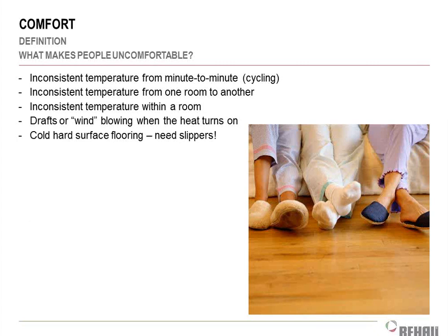Touching cold surfaces. If it's summertime, you like walking on the cold tile floor of your kitchen or whatever. But if it's wintertime, cold surfaces feel cold. Conductive heat transfers directly up through your feet into your body. This happens not just at home, like the example we're showing with the people in the slippers, but it happens at work too. If you're standing on a slab floor like I am right now, and the slab in this office is about 58 degrees, and I know that because I measured it because I'm anal, right? 58 degrees does not feel good going up through my feet all day long. So there's things like that that affect your ability to be comfortable.